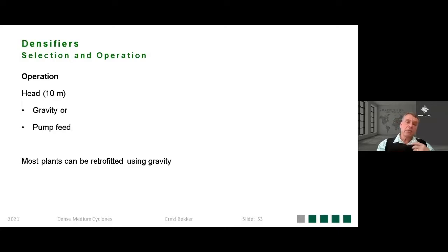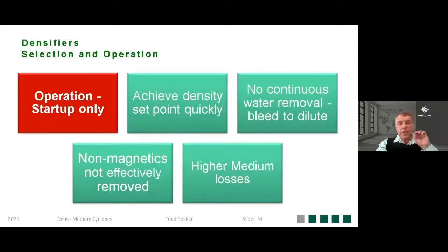When you're operating densifiers, we work on 10 meters physical head. We don't relate it to the cyclone diameter or the pipe densifier diameter. It's a physical 10 meters. It can be gravity fed or it can be pump fed.